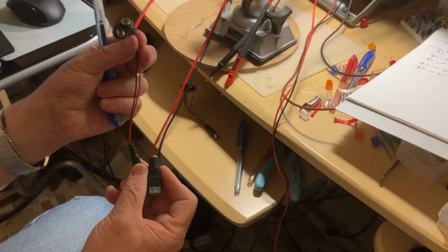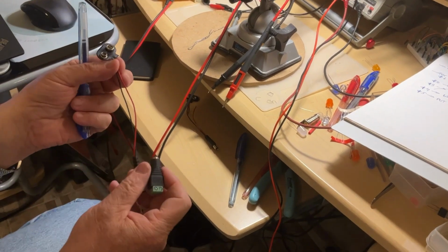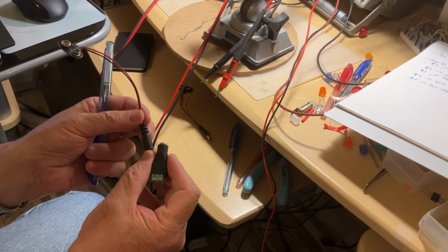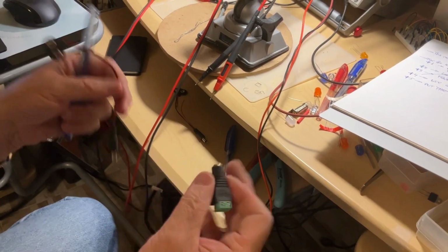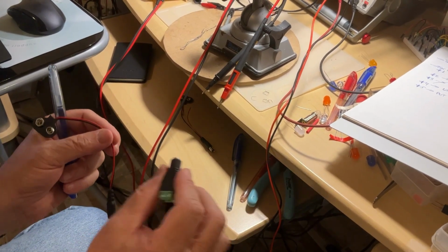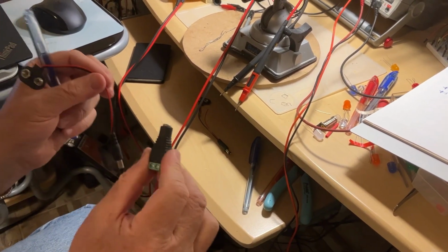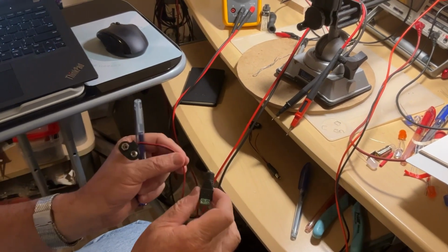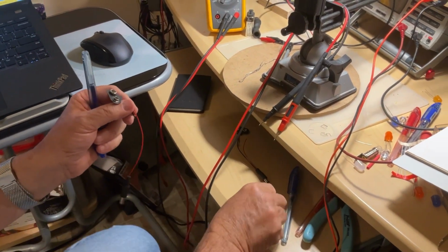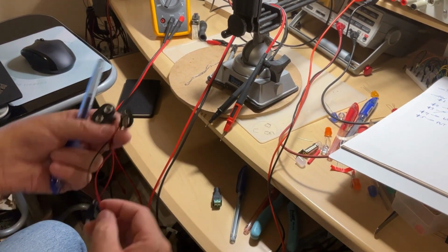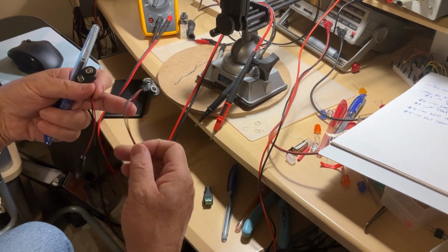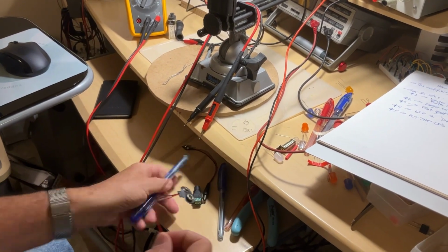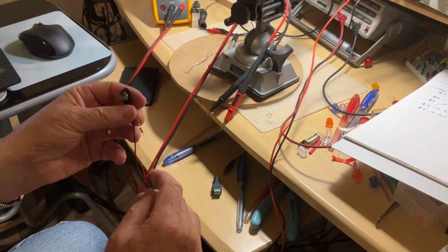Now, what is the trick about that? Don't connect a battery here to measure the LED directly, because you're going to keep burning LEDs one after the other. Remember that for any diode, it doesn't matter what kind, you need a limiting resistor. And I started to build actually using the same kind of connector, and I stopped because I realized I want you to see how it is done.